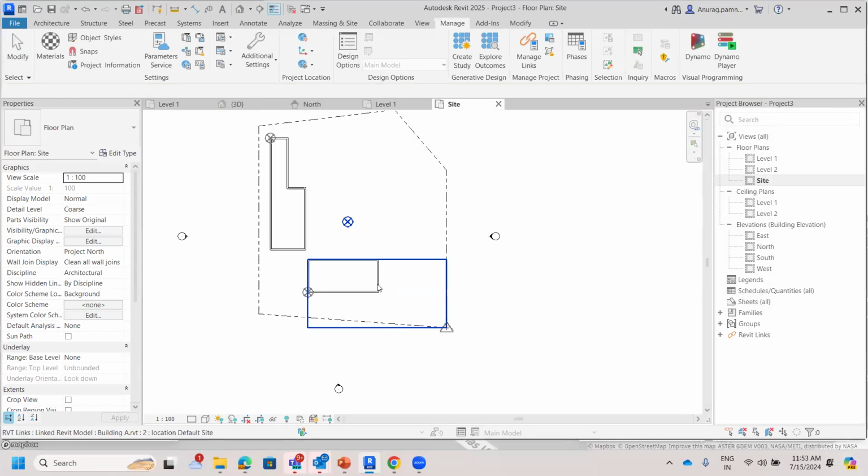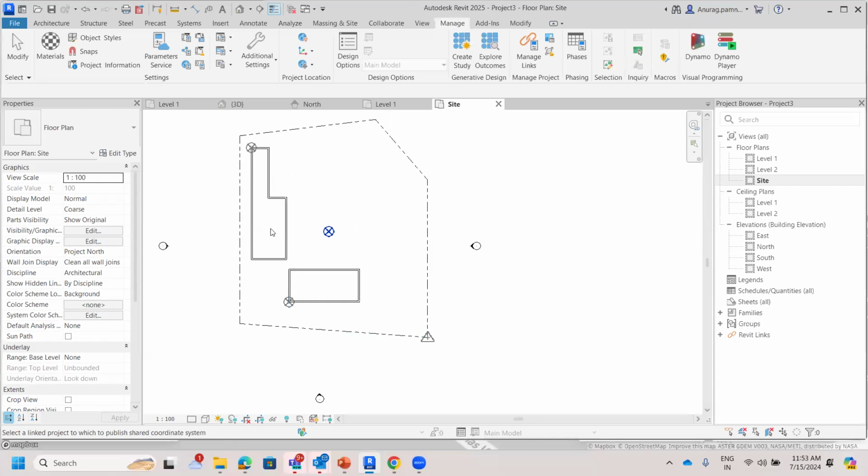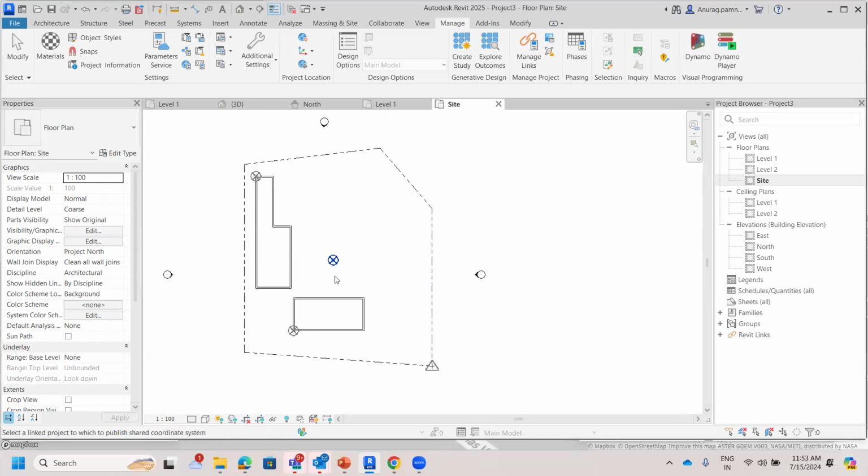So now all the other blocks have the same shared coordinate point, which is your survey point, and have a different base point. That doesn't matter somehow, because base is starting from 0, 0. Eventually, those models which have building A and B have been modeled into the same place. So the base point over here doesn't matter, but the survey point matters.